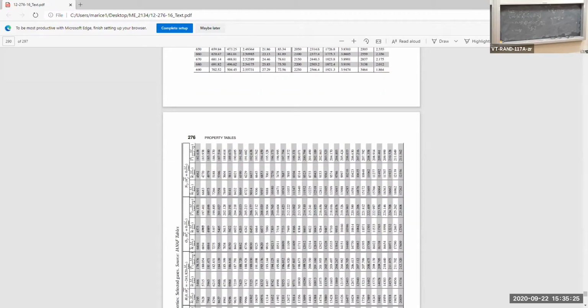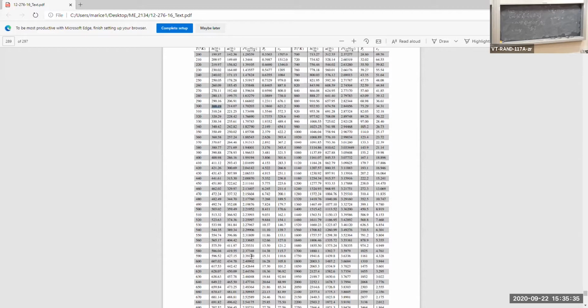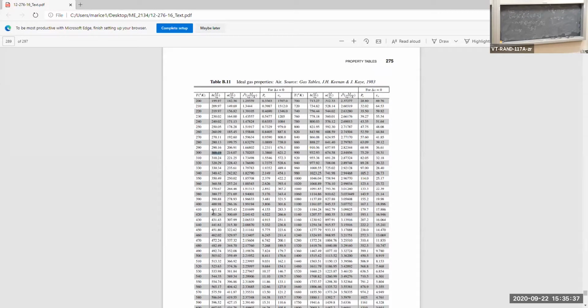If you go to higher temperatures, let's say 2,200 degrees Kelvin, the specific enthalpy is 2,500, not 2,200. So I'd rather you didn't use the rule of thumb of taking the same numerical value as temperature. I'd rather you actually came to the table and extracted the proper specific enthalpy.